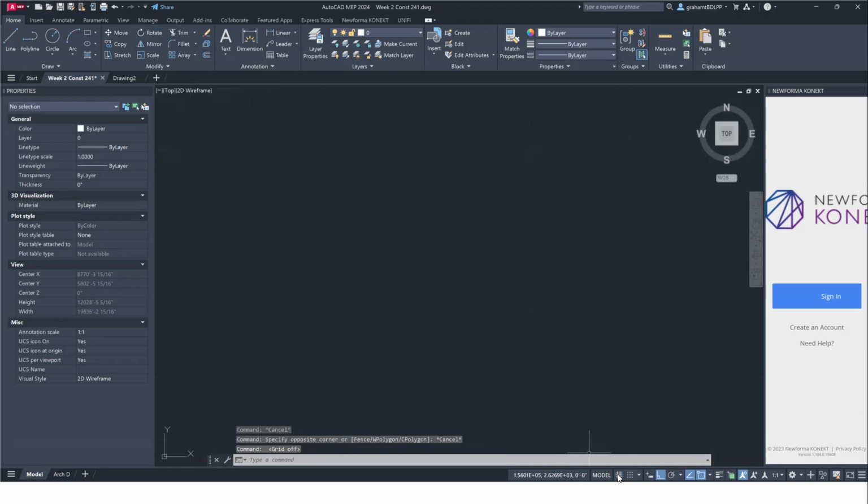The next thing that you're going to see next to the grid is these dots. This is snap mode. If I turn the grid back on, and again, you can barely see that grid, but if you use this snap tool, when you draw and move your mouse around, it will want to snap to the grids, and maybe the grids are certain lengths apart.